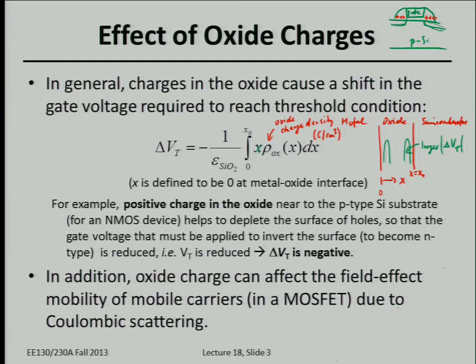So then we can implant some oxide charge, purposely put lots of charge in the oxide to induce an inversion layer up here. That acts as a very shallow source drain conductive layer, right? But that's still research. Nobody's doing that in production, I don't think, yet. But in general, no, we don't want to purposely introduce charges in the oxide, because usually you do that by implanting, and that might damage the oxide, so it actually doesn't act as a good insulator.